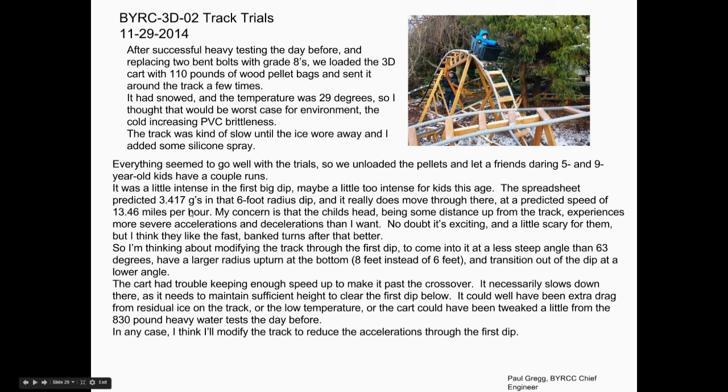I put my smartphone in there with accelerometers and checked what the real accelerations were. At first, like I said before, the first dip had like a 6-foot radius in it. It was really tight, and it was getting 3.5 Gs through there. And I thought, well, that's a little too much. So I don't really need that 63 drop angle.